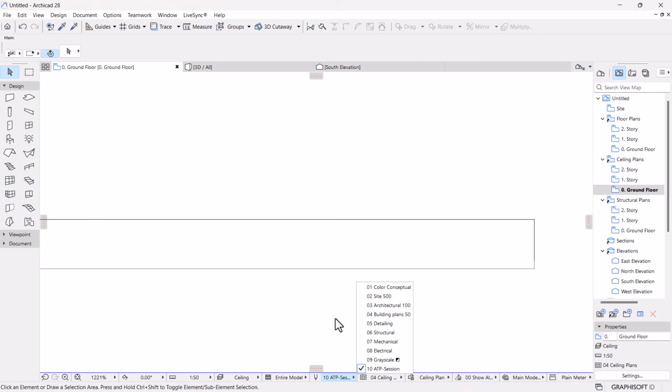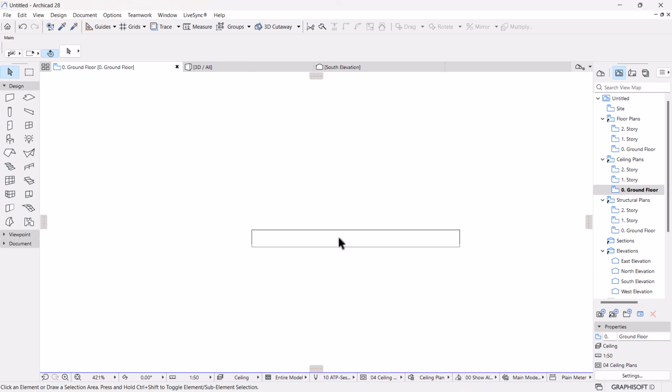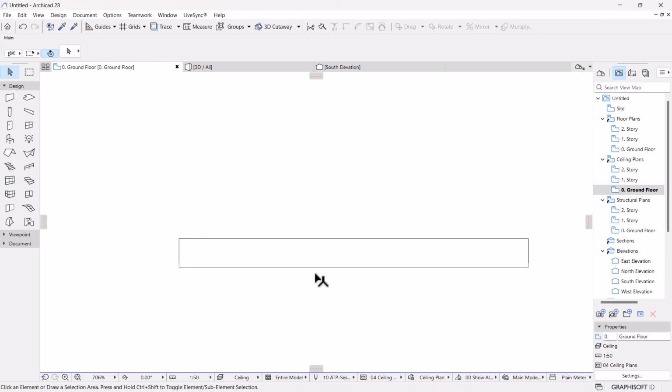So like I'm saying, if you're changing that, make sure you understand this is structurally or systematically assigned to elements, because at the end of the day you don't want a situation whereby you change the pens in different views and then it gives you a different graphic feel because you didn't respect the hierarchy and the color table when creating your custom pens.